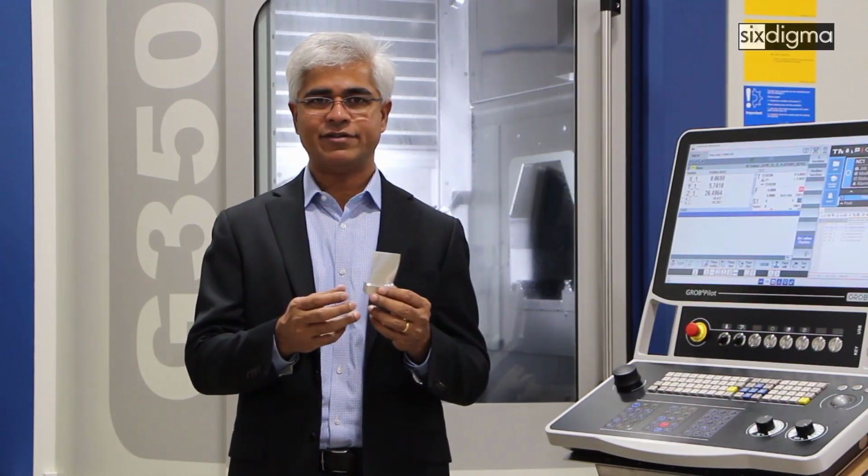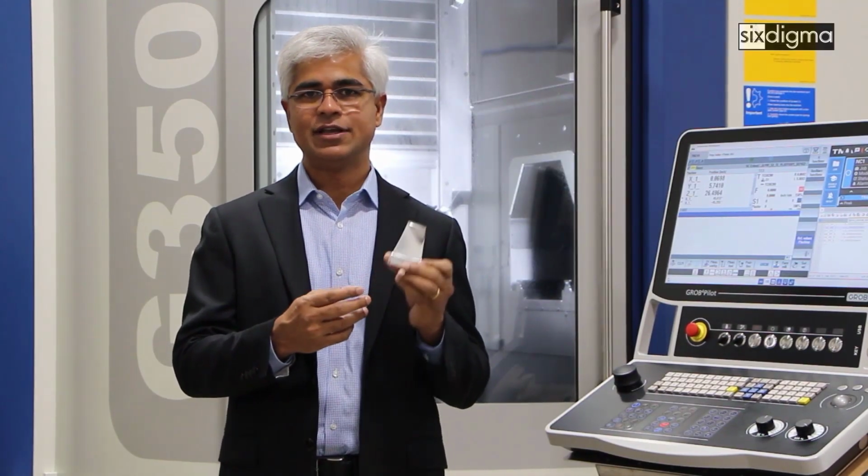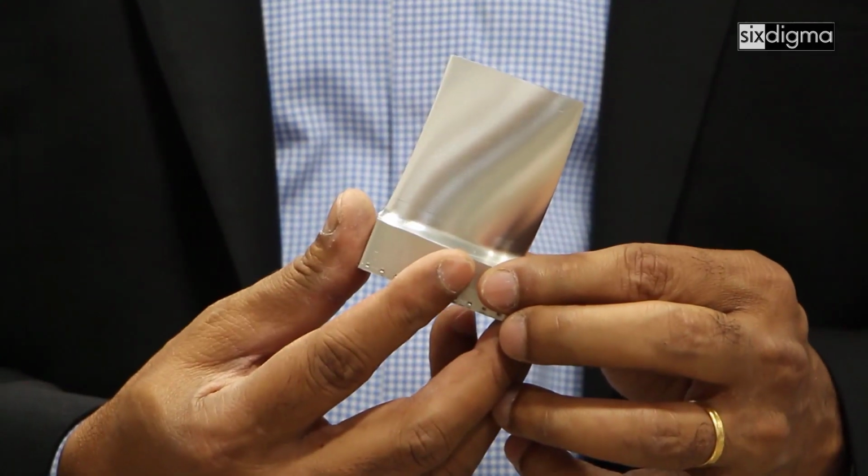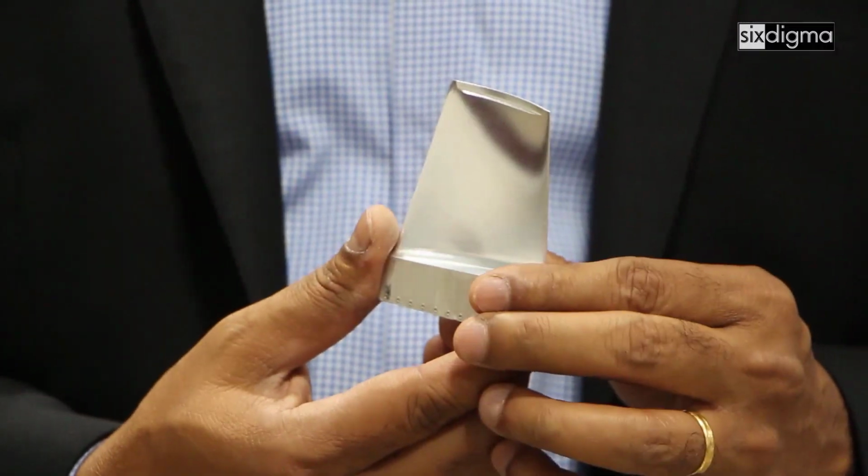Even though this airfoil looks really smooth, during engineering design, various manipulations of these surfaces introduce all kinds of surface imperfections, curvature reversals, and other artifacts that make it extremely difficult to machine these parts and produce a really smooth surface on the CNC machine. This, combined with tight tolerance requirements on these parts, makes it an even bigger challenge.